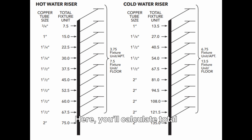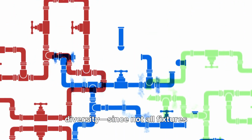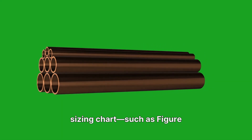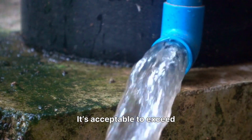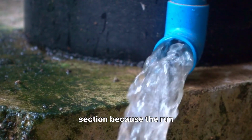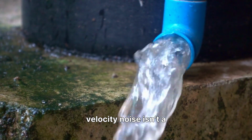Here, you'll calculate total fixture units using column A of figure 1.1. Add 75% of the cold water fixture units and 75% of the hot water fixture units for each fixture that requires both. This adjustment accounts for diversity, since not all fixtures operate at once. Then, use the appropriate sizing chart, such as figure 3.3 for copper pipe, to select your street supply size. It's acceptable to exceed the 5 psi per 100 foot rule for this section because the run is typically short and located outdoors, where higher velocity noise isn't a concern.